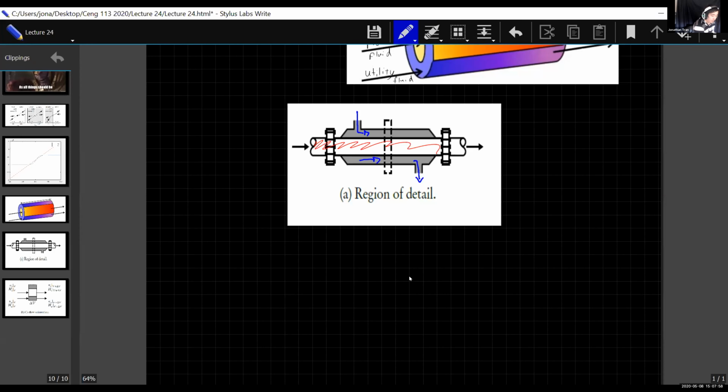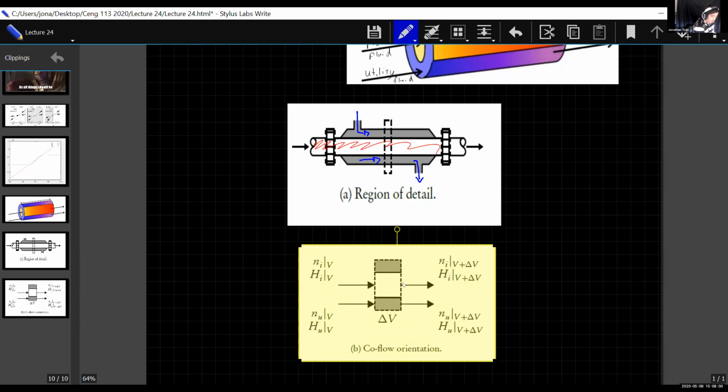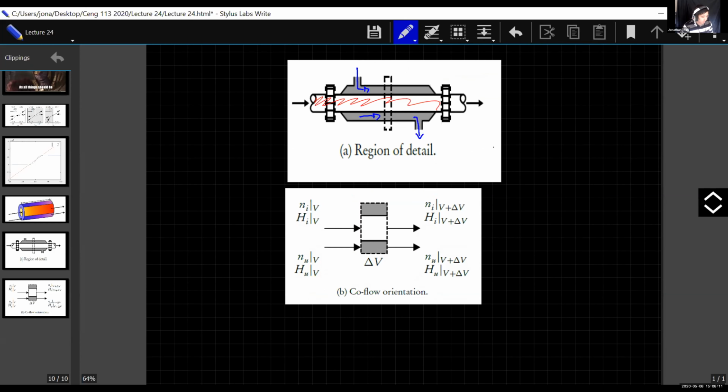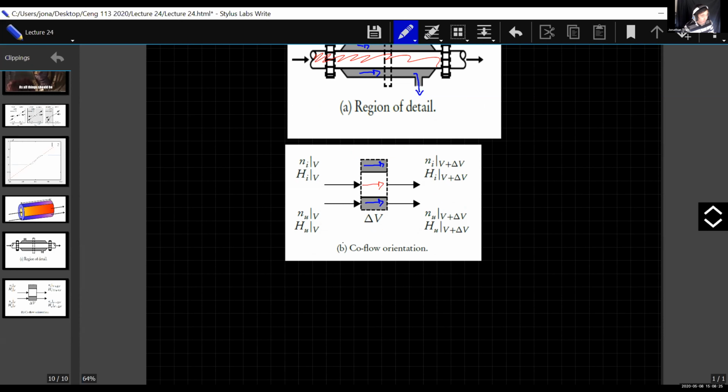And when we write this in terms of an energy balance, we can look at a cross section of this whole pipe setup with a jacket, similar to how we did with the energy balance when we derived that in chapter 7. And here we can see that in this case, this white section in the middle is still our process fluid, and the gray areas on the outside would be where our utility fluid exists. And so we can write an expression here that will define our energy balance for the utility.